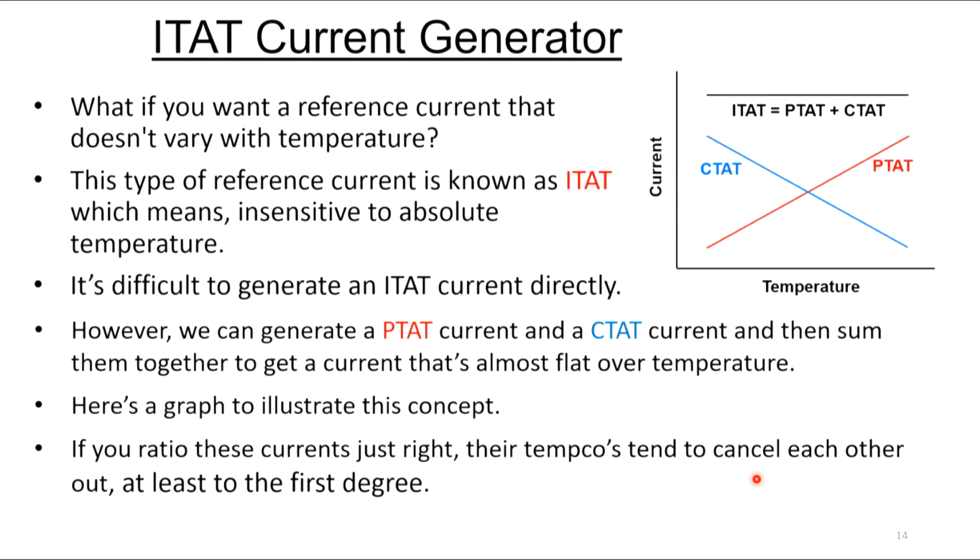That's correct. You always have to take into account the temp code of the resistors. We have resistors with positive temp codes, with negative temp codes, and with near zero temp codes. And in fact, you can mix and match positive temp code and negative temp code resistors together to generate a zero temp code resistor if you really want one. But good question. Thanks, Dave.